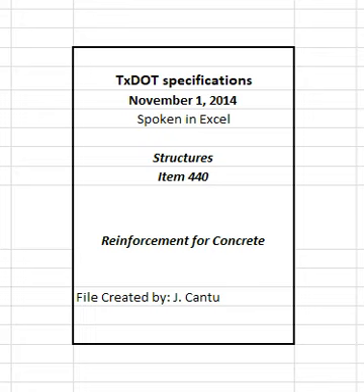Sample and test couplers for use on individual projects in accordance with DMS 4510, mechanical couplers for reinforcing steel. Furnish couplers only at locations shown on the plans. Furnish couplers for stainless reinforcing steel with the same alloy designation as the reinforcing steel.